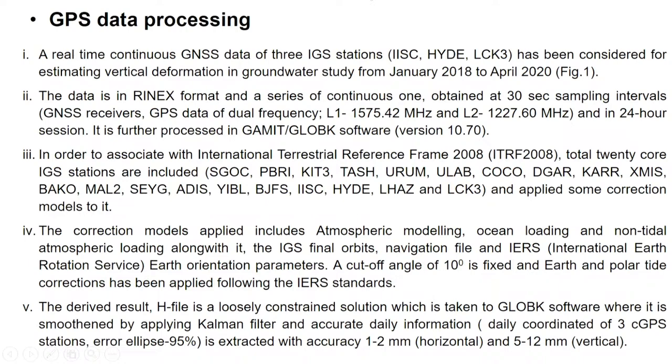So these are some steps of GPS data processing. There are many open source software packages available for geodynamics study, like GAMIT/GLOBK is there, GIPSY is there, and Bernese is not open, you have to purchase it. It is GUI based software. So this software is the standard software for geodynamic study.